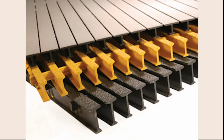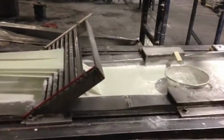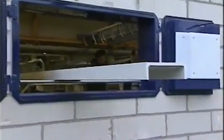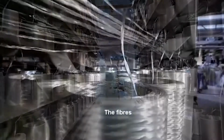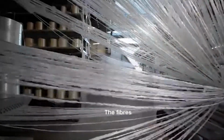Other profiles unique to the pultrusion process are also available. Similar to extrusion, the pultrusion process consists of pulling bundles of fibers through a heated die in the shape of the finished piece. The resin-saturated fibers are highly compressed by being pulled through the die, which forms an extremely dense composite. The fibers are continuously drawn from spools called creels.